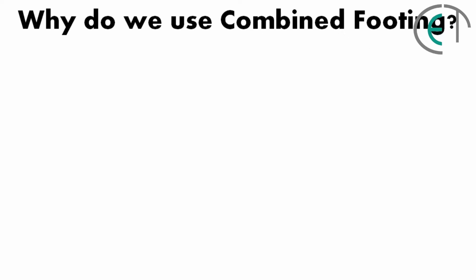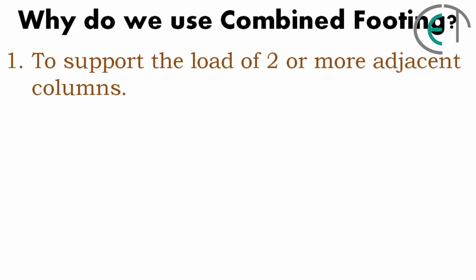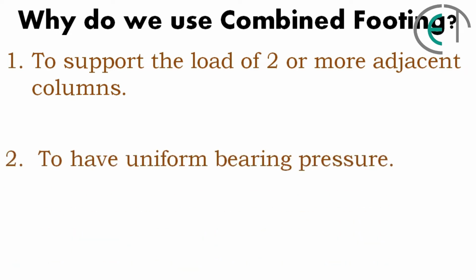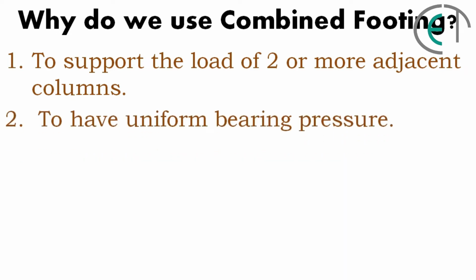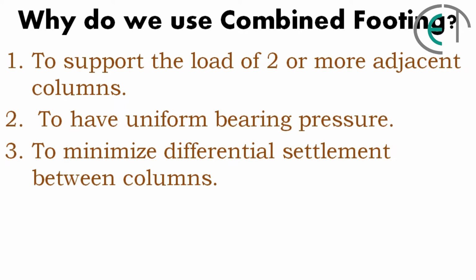Now let's talk about why we use combined footing. To support the load of two or more adjacent columns. To have uniform bearing pressure. To minimize differential settlement between columns.